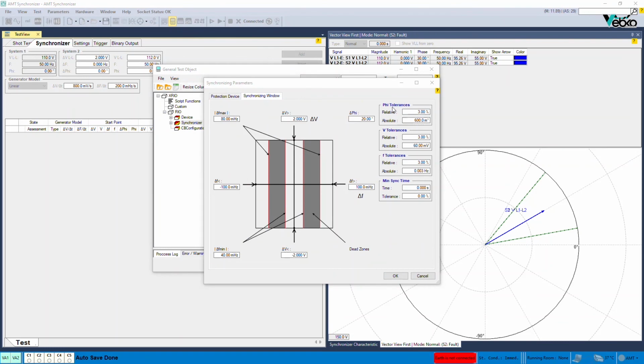About the voltage that is being used for the test, it should be noted that the relays measure the applied voltage, and if the nominal voltage is as much as 110, the user only needs to apply VLE and VL2E for systems number 1 and 2 with the same value to the relay, and this can be viewed in the hardware configuration.